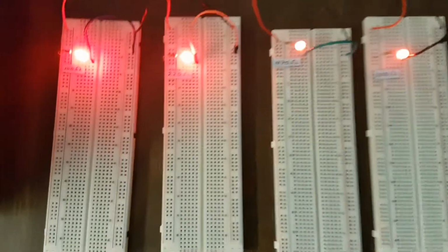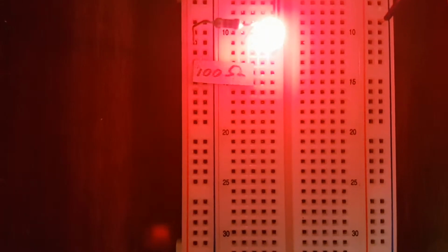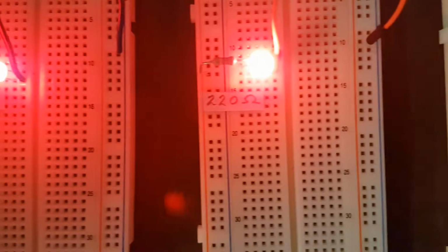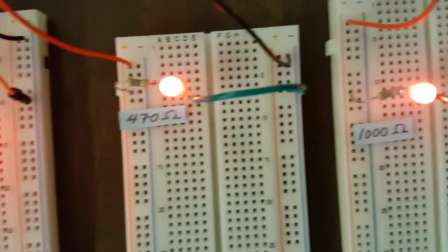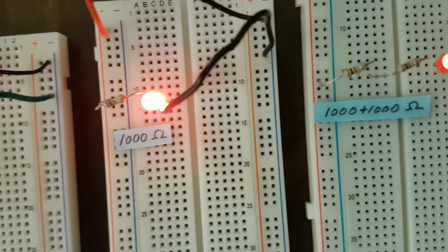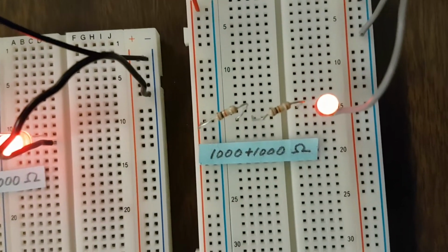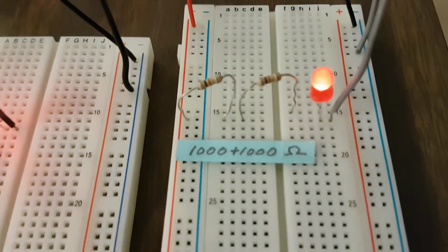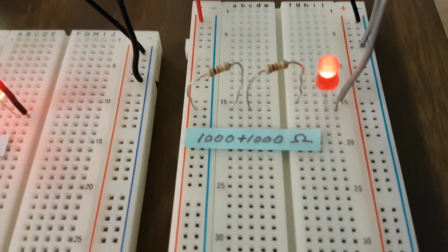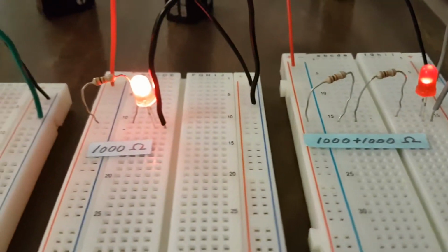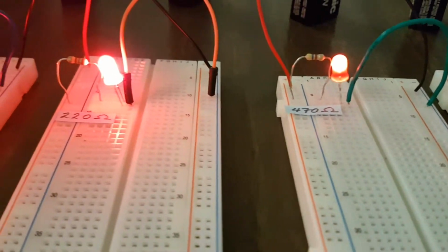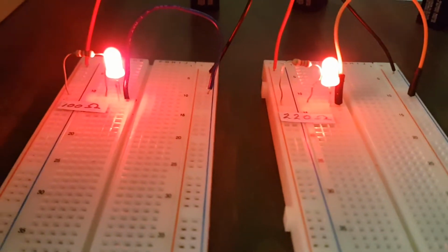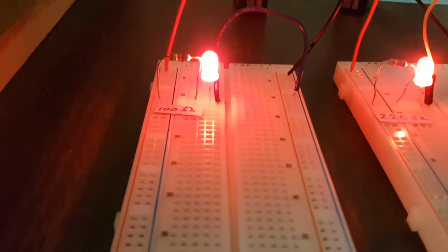at once. Starting off with the 100 ohm resistor, you can see the brightness of the LED. Moving on to the 220 ohm resistor, then the 470 ohm resistor, 1000 ohm resistor, and then where 2 resistors are hooked up in series, which is 1000 ohm plus 1000 ohms. And you can hopefully see that there's a difference as you move from the smaller numbers to the larger numbers, and now we're back to the smallest number, 100 ohm resistance